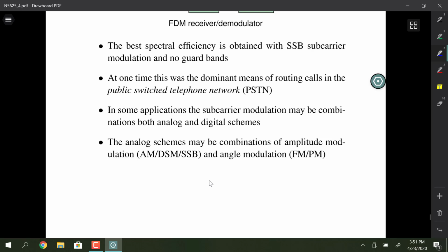and then at the other end they would get taken off, and they would actually relay all those signals over microwave towers. So they would modulate the subcarriers using FM, I think is what they used most often, onto a carrier, and then at the other end of the tower they would demodulate it and then do what they needed to do before they sent it on further across the country.